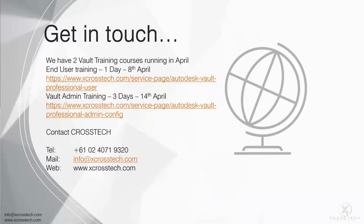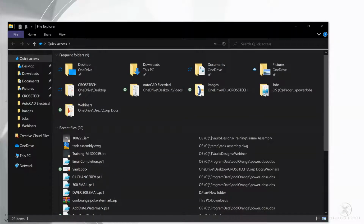Can changing a category or file trigger actions according to rules? Yes and no. Not out of the box, but coolOrange can do it. Can changing a file's attribute trigger a change of the file's category? Yes, within coolOrange you can do that, but you've got to set it up in a script. It's pretty straightforward to change the category. I'll show you the PDF script and briefly what it does.